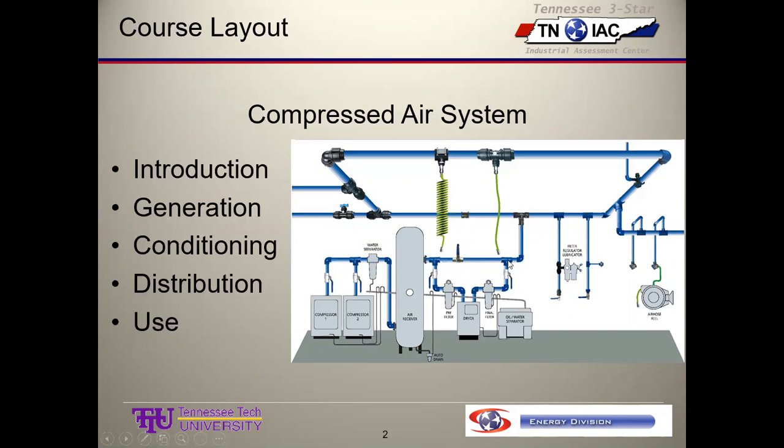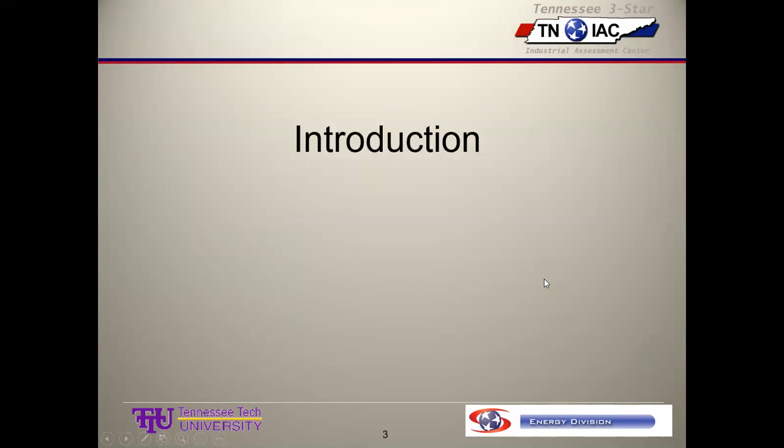We go out to our system and then we feed up, and our distribution system is actually a loop, which turns out is a very, very good idea. We show some taps coming off of the top. You really don't want to come off the bottom, if you're bringing things down, any more than you have to, because that's where moisture and dirt and such will accumulate. So anyway, that's just neither here nor there, I guess.